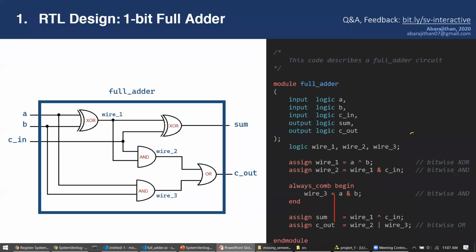Then, can we do the exact same project using Quartus? Of course you can, but you will have to use Altera's FPGAs. If you have an Altera FPGA, you can't use Vivado. You have to use Quartus, and you can do the same thing there. But I will not be teaching how to use Quartus here, because the session is about SystemVerilog, not about the software. In Quartus you also create a project the same way, add the SystemVerilog files and sources, and you can do everything, including creating an IP.